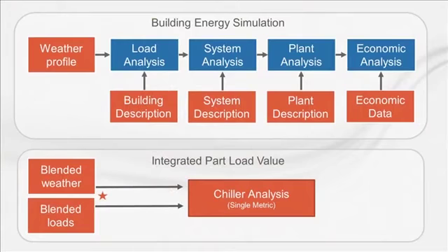To illustrate the limitations of the IPLV tool, I placed the block diagram of the IPLV calculation and the building energy simulation side by side. The biggest issue comes in with the blended weather profile and blended loads. For weather, this assumes that throughout the entire United States, the outside temperature at any given moment is the same.